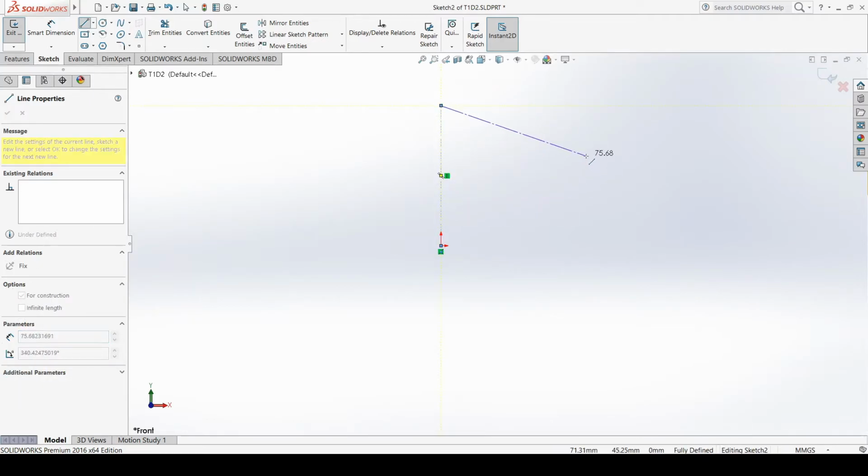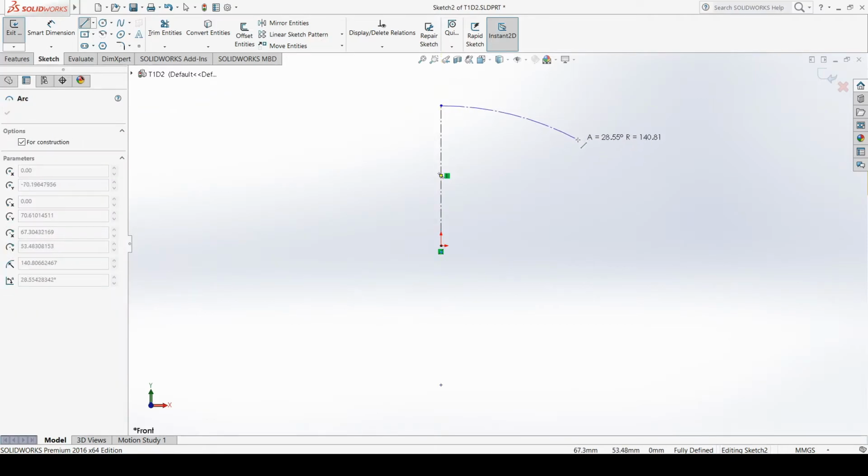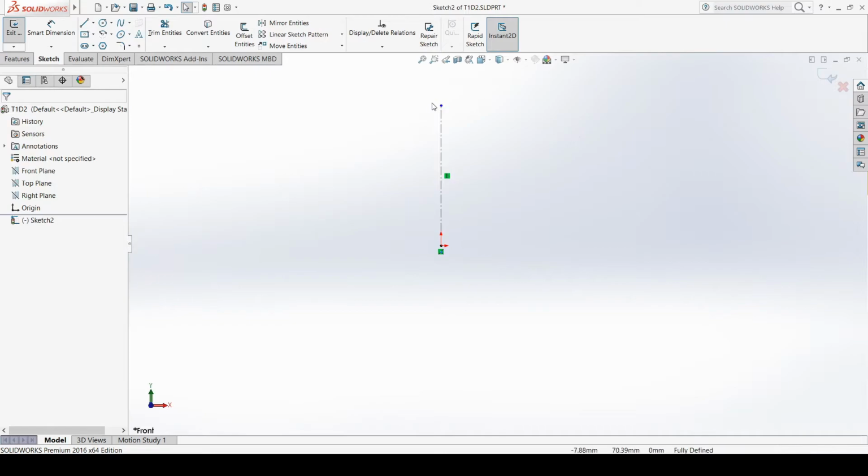maybe up to this. So you see, whenever you have clicked here, this line icon, it's not finished actually. So we need to select the solid line from the menu bar. To escape out of this, I will click the escape key on my keyboard. Now we are free to select any other options. So right now click on the line